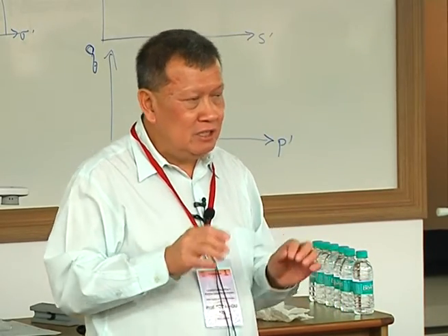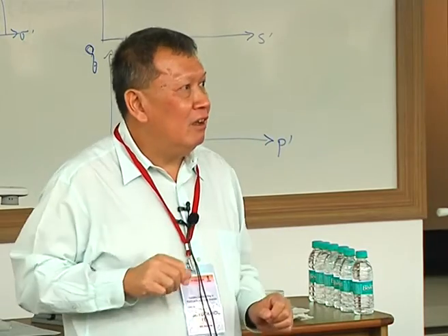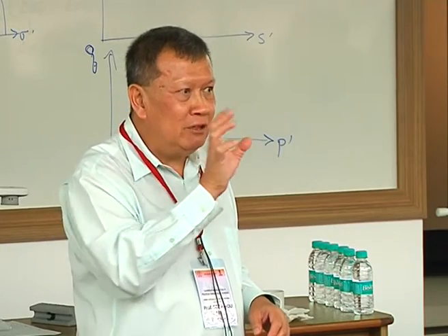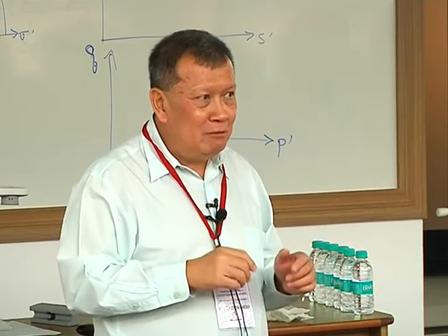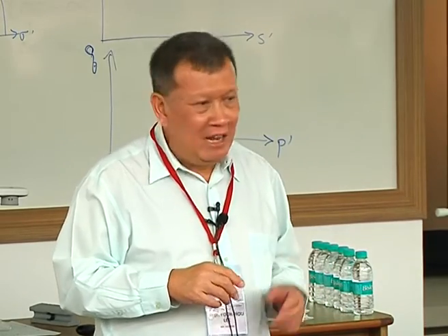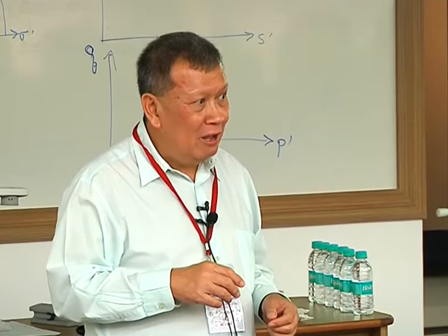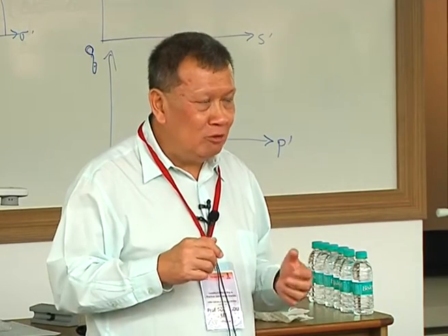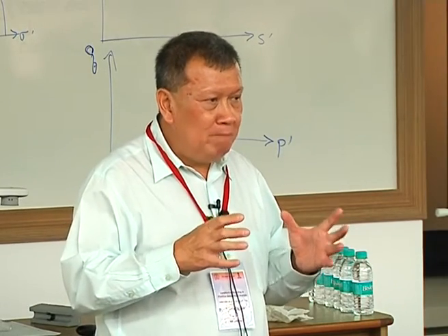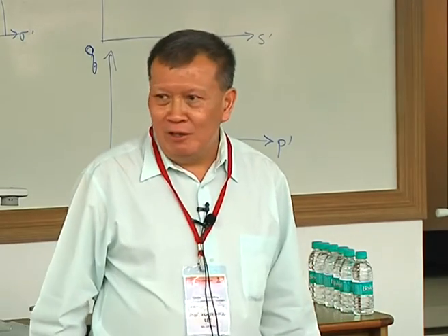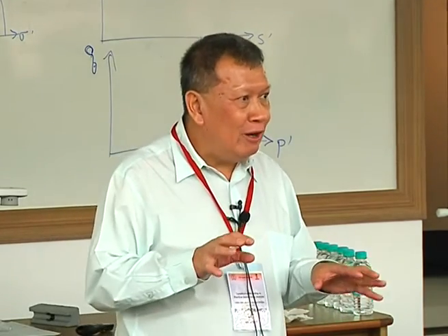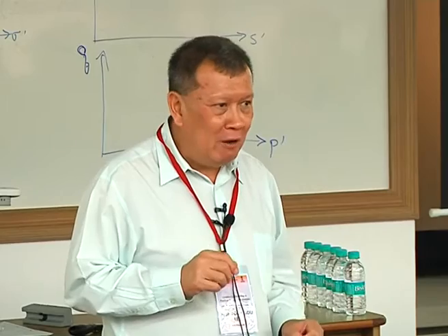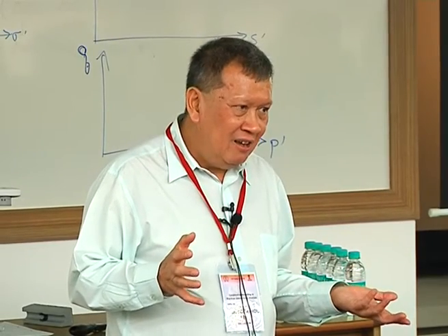The main thing in the exercise is not to let you generate the mesh. I give you the mesh, you change the material property, and you rerun that. Then by assigning different material properties to the problem, you'll see how a triaxial test comes out looking with different material properties. The mesh I give you is actually nothing more than a triaxial test. And that is the first step. To me, that is a very nice, simple first step that all engineers starting with FEM should do, because you have to explore the material model first, using a simple problem that you know very well. And what is simpler than a triaxial test? You know what I mean?